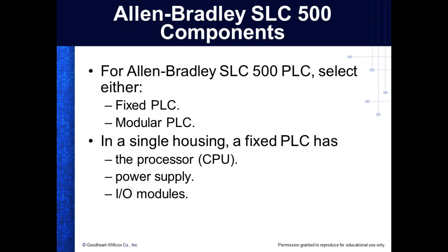But this guy here, the initial investment for these would be more. But on that, if I lose an input or an output, I got to replace the PLC. Over here, I can do what? I can replace the module, right? You understand? So these are cheaper to maintain.